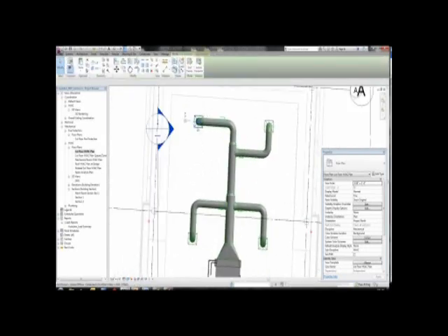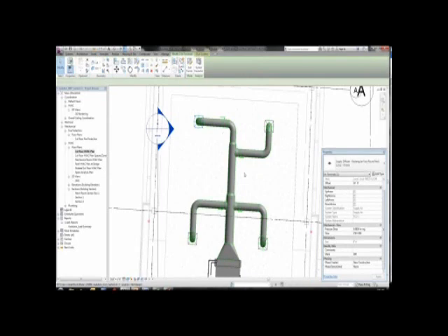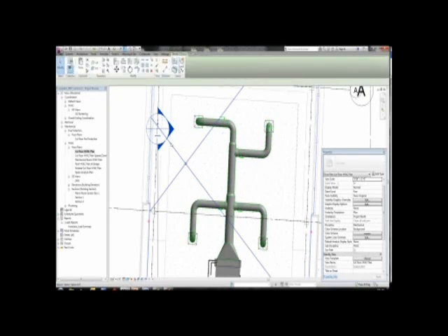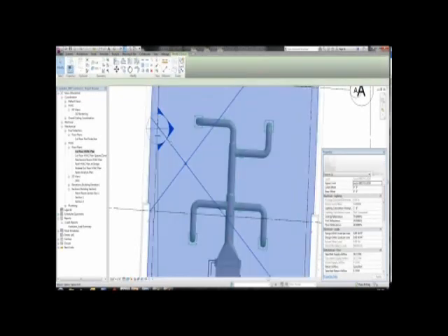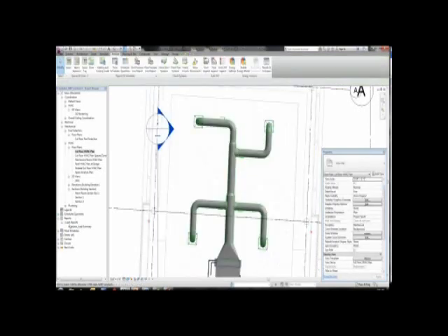All right, now we're going to take a look at the room calculation point. So as I click on that diffuser, I'll scroll down, you can see that I have a flow inside the diffuser that I've specified for 150 CFM. Right, so I've done that for all of the diffusers that are in there. But as I click on the space, let me scroll down here and take a look under the flow, you can see there's the 513 CFM that's calculated for the system, but the actual supply isn't registering the 150 CFM per diffuser.